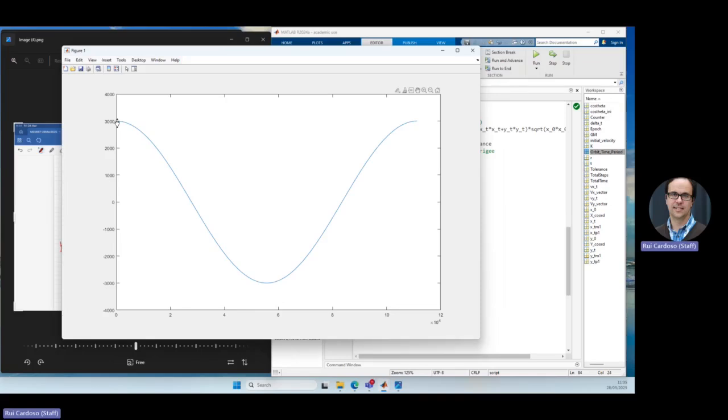Vy. Yeah, look, you can confirm some points. Horizontal axis is time, don't forget. Time 0, your Vy is 3000 meters per second, right? And then it decreases. So this point here is the apogee, right? And then it starts increasing again, reaching 3000 again when it completes the orbit, right? And then the next time it keeps getting this profile. And for magnitude, you have to do the square root of both of them.